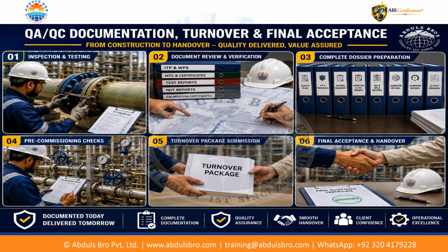Let's see what are the QA/QC documentation, turnover, and final acceptance. Piping QA/QC is complete only when objective evidence of conformity is properly documented and traceable. Quality records include material receiving inspection, RFIs, welding or joining records, NDE reports, pressure test documentation, NCRs, and corrective action records. Outstanding deficiencies and punch items must be resolved, reinstatement verified, and applicable as-built documentation completed. Following the final walkdown, the approved quality dossier supports mechanical completion, system turnover, and final acceptance in accordance with contractual